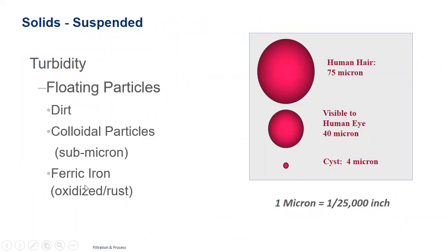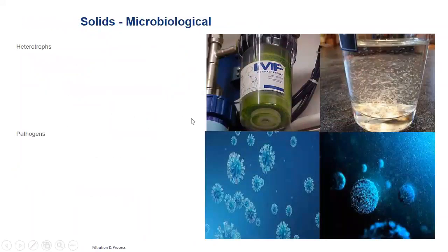And depending on how you form that stuff, it may be colloidal or it may be heavy enough to fall out of solution. We want to manage this dirt load and remove it with relatively cheap sediment filters compared to the rest of a treatment train. Manage dirt load cheaply. Why? It's your dead frogs, logs, and twigs. Very, very easy to manage with mechanical means.